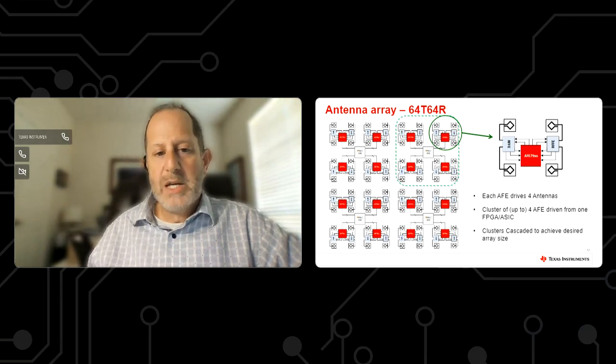And with this tile, we can optimize certainly the clocking, certainly the power solutions, have 1 power solution that can support the FPGA and all these RF sampling transceivers in 1 solution. Okay, so now we've got a 16T, 16R tile.